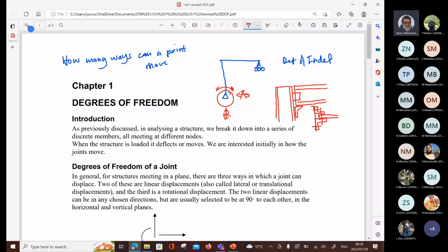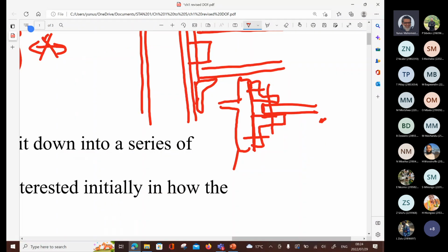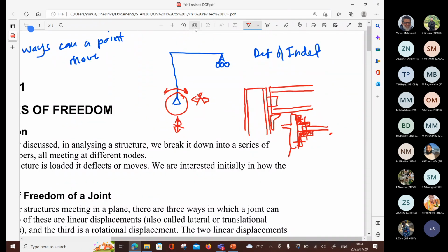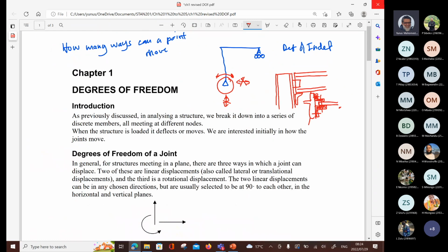Let's set a nice line there. Okay, so that's your column going out that way. So that's the column. You have this, what do we call it? Cleats, right? So these are the cleats here. And they hold the beam onto the column, if you follow what I'm saying. And this is the single bolt going through. So that would give you a pin connection. Right, so in steel we could do it that way. That's again not a perfect pin, but something very close to it.